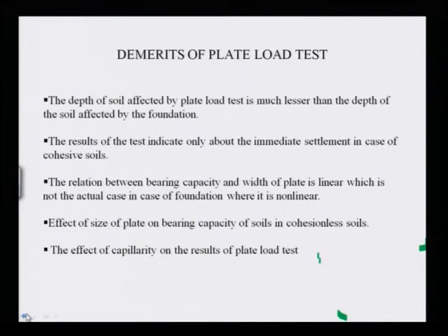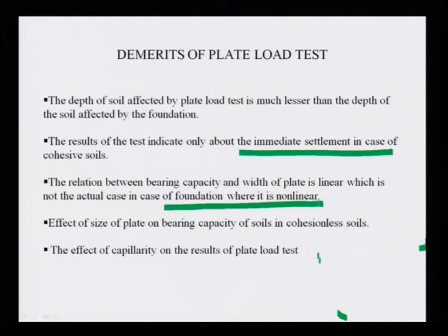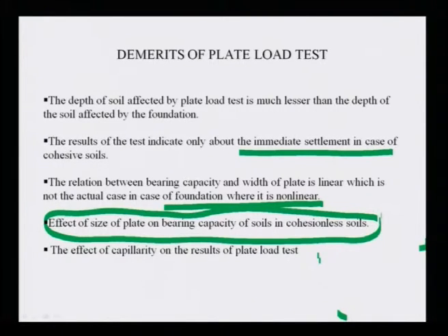Then the results of the test indicate only the immediate settlement. The relation between bearing capacity and width of plate is linear, which is not the actual case for a foundation, where it is non-linear. The effect of size of plate on bearing capacity of soil in cohesionless soil is called scale effect. Then there is the effect of capillarity on the result of the plate load test.